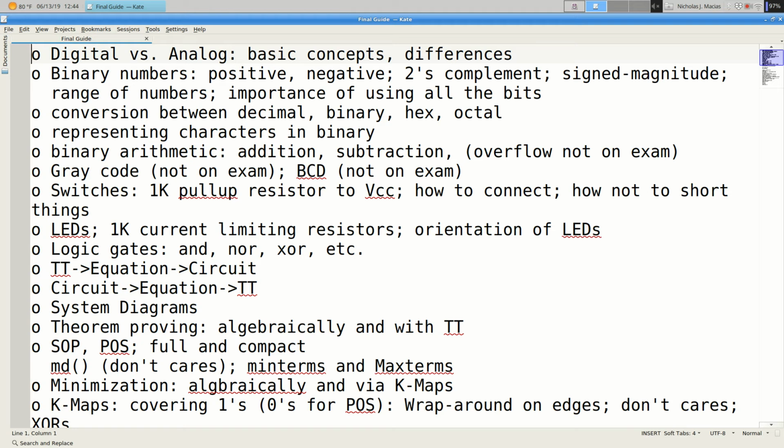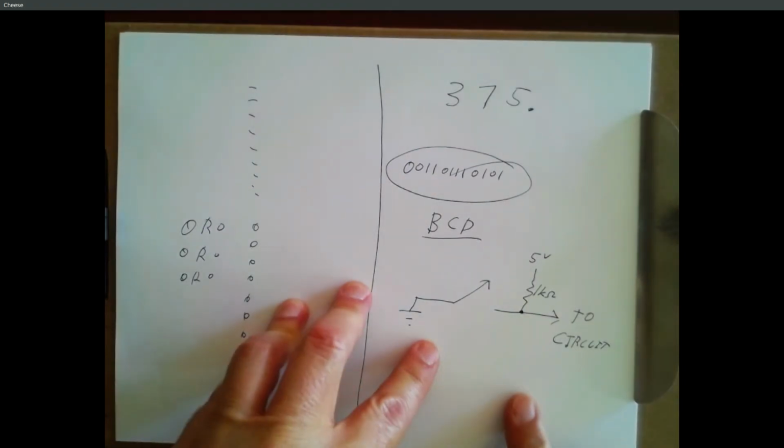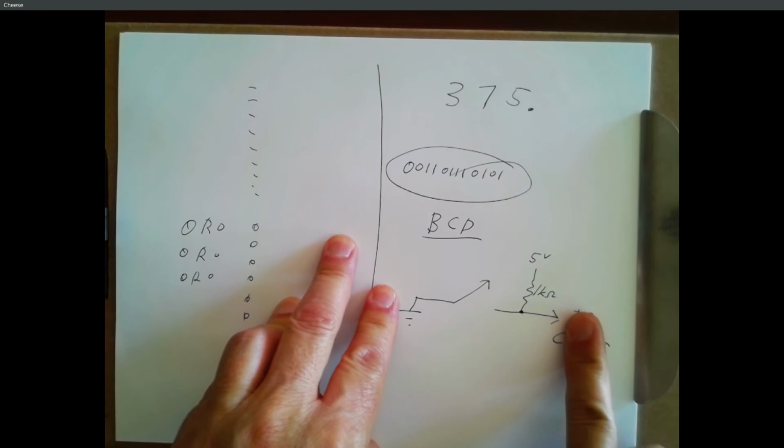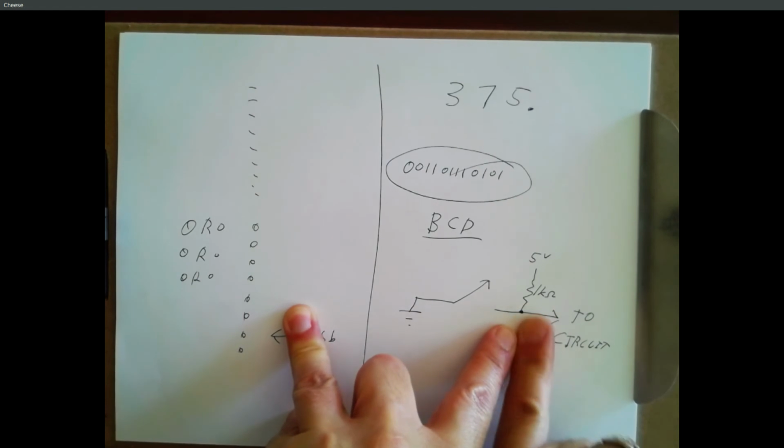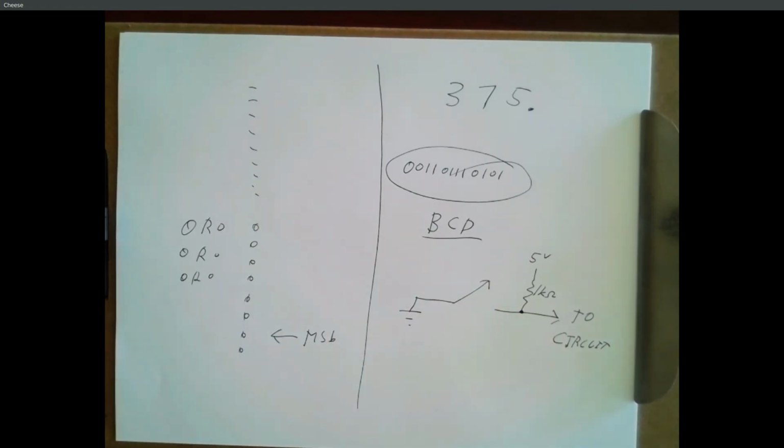And if you've got 3 switches, make sure that you're not somehow shorting your inputs together. Right, so your easiest way to make 3 switches is just replicate this circuit 3 times. Right, if you try to share this point with all 3, you're shorting your inputs together, right, and then your circuit doesn't work right. So just do this for every switch and you're safe.